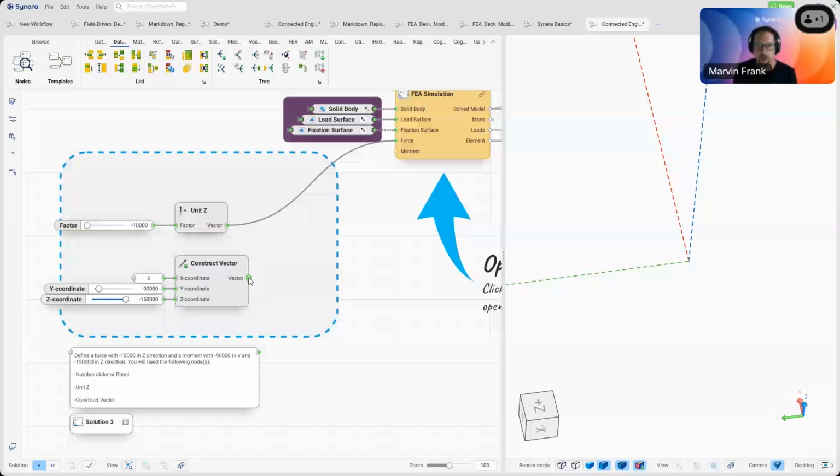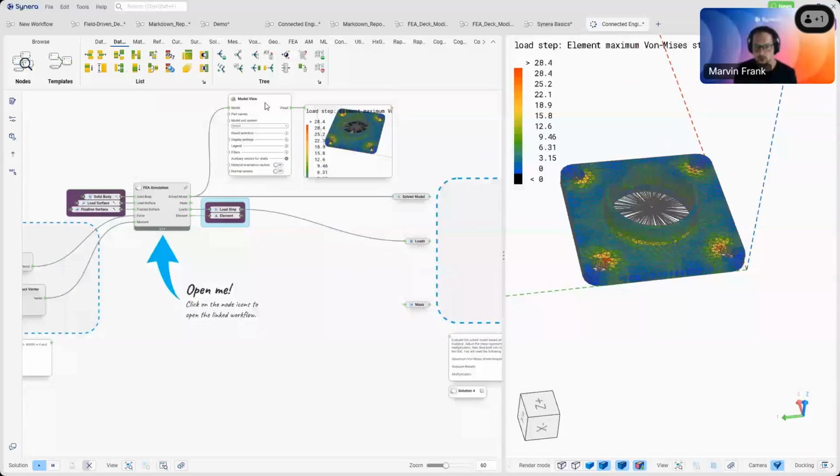So here for the stress response, these are part of this design exploration. That is a powerful tool, and I will first give you a quick insight here. So it consists of a parameter setup, and that has this width and radius of the cylinder as design parameters. Those were highlighted in the beginning with this purple edge. Then we have the mass response and the stress response. For this, we need this stress response nodes here. They are already set. But what we haven't set is the definition, so the value.